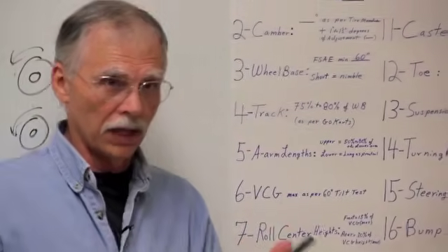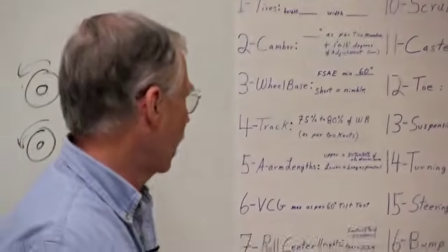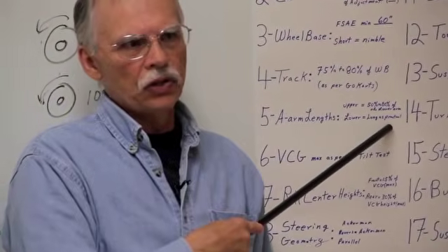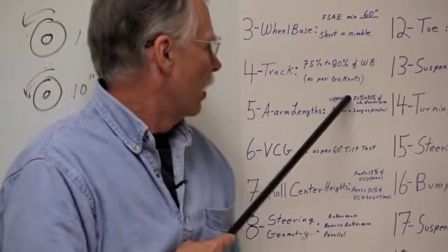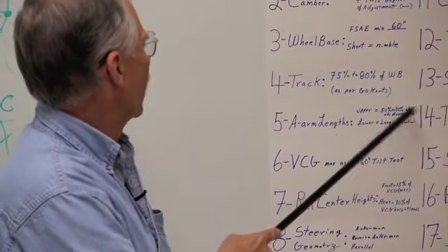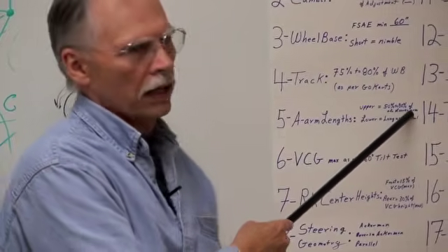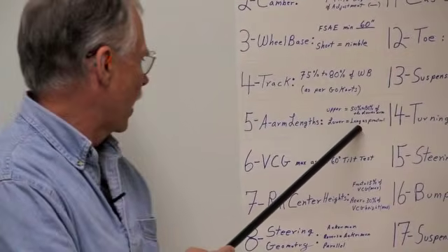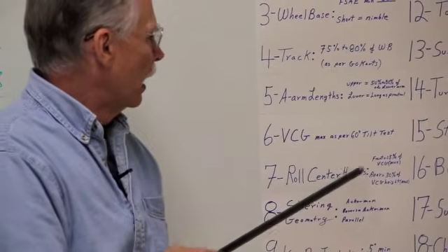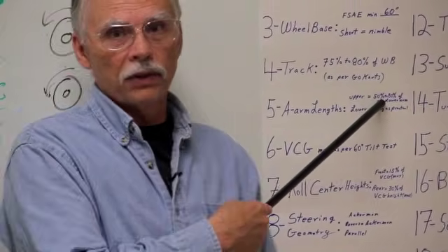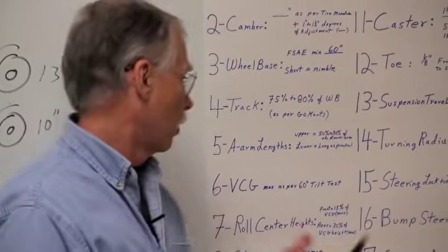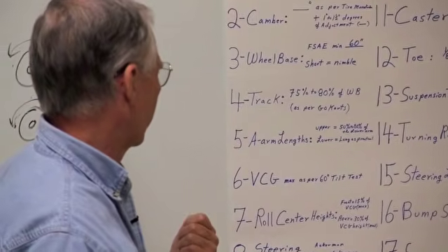You have to have something called rising camber. So a long lower A-arm makes that easier to achieve. The upper A-arm should be between 50 to 80% of the lower A-arm. The reason for that is something we'll get into in a little bit called roll center. If it's outside these parameters, you probably aren't going to be able to create a geometry that's suitable, or as suitable as you would like to have.